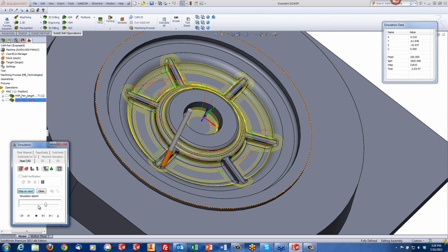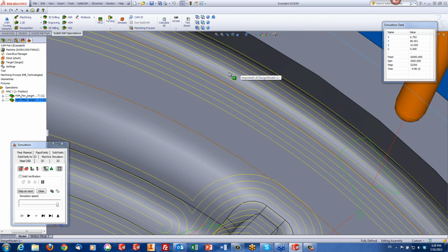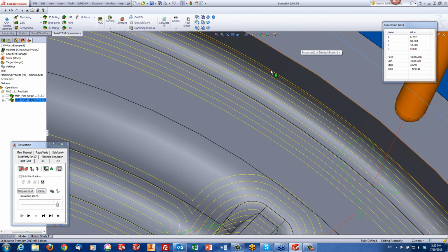If we take a closer look at the simulation itself, at the toolpath that was formed, let me just zoom in to this area. You'll note I said 5 steps in total in each direction. We have 1, 2, 3, 4, 5. Remember this one in a moment. We'll go down from the other side. 1, 2, 3, 4, 5. And this one is the actual pencil milling toolpath that's done. We have the pencil milling toolpath plus 5 step overs in each direction.